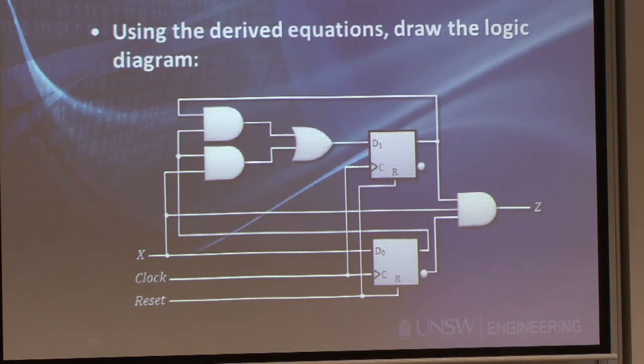One element that's sort of new to this whole thing is this reset signal here. Now, in the very last slide of last week's lecture, we talked about direct reset and set signals. In this case, this one will be a direct reset signal, active high direct reset. And this is a way to actually put our machine into its reset, its initial state, when we power it up.